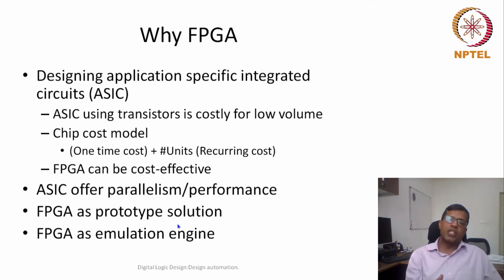So you will observe that for a simple logic, an FPGA would require probably 8x to 10 times more area. It would be slower also, but because it could be a cost effective solution, that is why FPGAs are predominantly used in industry. Primarily they are called a prototyping engine because they can serve the requirement to prototype a particular design.